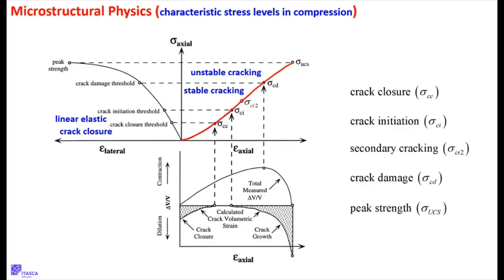And you slowly move the platens together. Typically the bottom platen doesn't move and the top one is slowly pushed down. And as you push down, you're measuring the force pushing back. You divide that force by the cross-sectional area of the specimen and you say, that's my axial stress. That's what you're measuring. And you're applying axial strain. You're applying displacement from the top. And you're doing this very, very slowly.